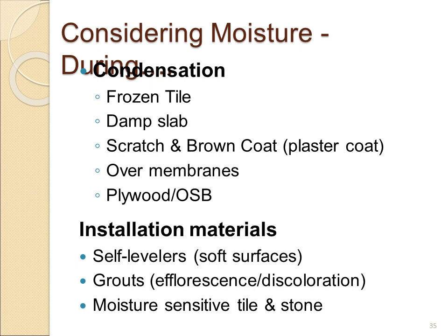Well, many times the surface of plank tiles are variegated or profiled, and what happens is the water or moisture from your last cleanup is sitting there. And if the temperature is just right, the moisture will stay there, and it'll finally run off into your grout joints, and the moisture that goes into the surface of the grout can discolor it or actually make it cure out soft. So a good practice with plank tiles is to do a nice wipe down with a towel after you're done grouting in order to remove all that excessive water and not have moisture affect the surface of your grout.